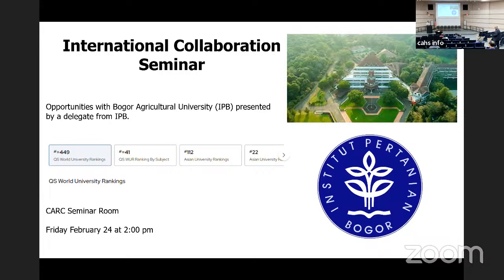Very good question. Now, to seal the cracks, they typically use asphalt patching, as I said before. TxDOT is also applying a different moisture barrier. So if I show you this figure. What TxDOT is trying to do is this: the main path of moisture movement into the slope is through the edge of the slope, right? So they are putting in a barrier-like thing, which extends from here down to a depth of almost 5 to 6 feet.